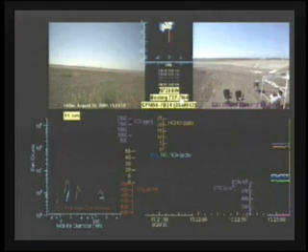As the plane goes in front of us, we read the tail number, which allows us to find out what airplane we're looking at, but also what engine is on it. Down here on the right, we're looking at a number of gas phase species, CO2 on the bottom, as well as the particle number count. That's a very good indication that we're seeing exhaust from an airplane engine. The middle panel is NOx. It goes up with power. The top panel is two products of incomplete combustion. We're measuring other ones, but these are ones that are there in high quantity. One is carbon monoxide, and the other is formaldehyde. So they'll tell us how much unburned hydrocarbons are coming out, and they go down with power. As we go up in power, the hydrocarbons disappear.